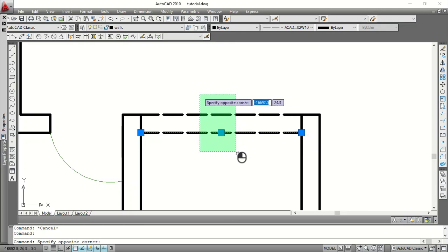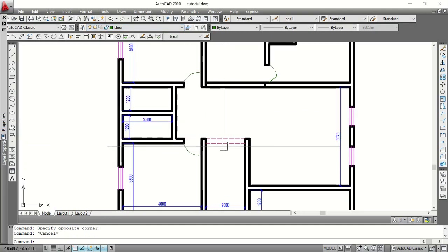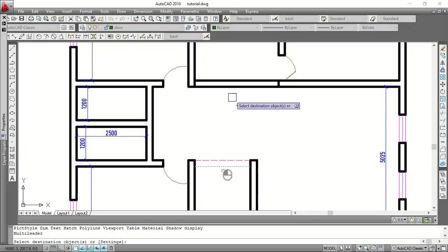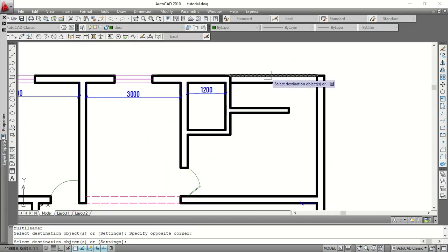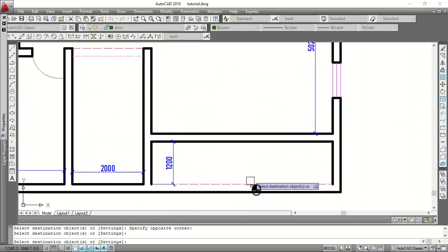Okay, so you can just quickly select it, come to your layer property and click on dash line. That's perfect. So I don't need to come and be doing this one after the other again. I can just pick match property, pick the property I want to match, then match it to anywhere I want to match it to. So you could see I didn't define this.